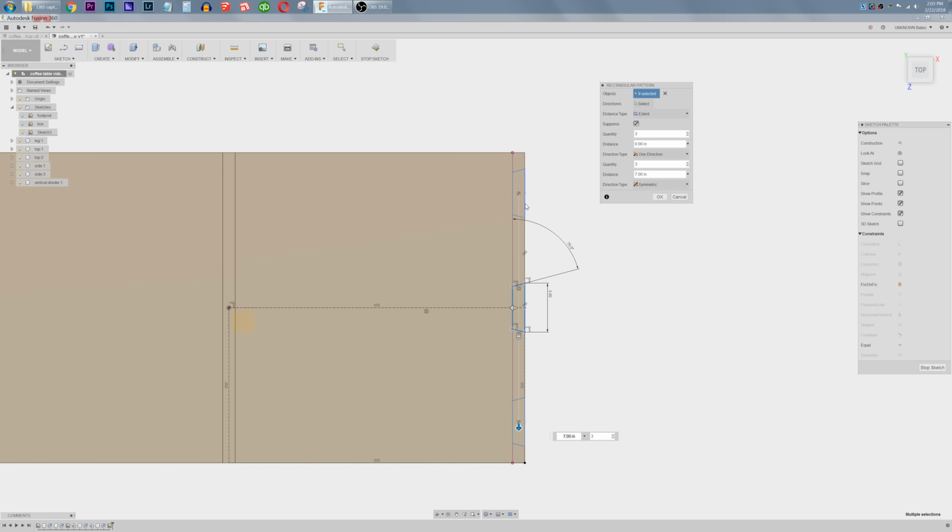So that's 3. I want more than 3, obviously. Let's add 4, and it puts 2 on bottom, 1 on top. Let's select 5. That looks good. 7 inches looks good. As far as the spacing, this gives me a pin in the middle that is smaller than the outside half pins, which I actually like. That creates a half pin on the outside that is a little bit stronger.